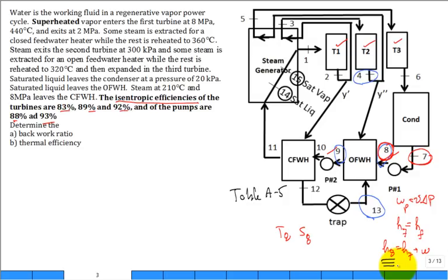I got h8, pressure at 8. So you got the pressure at 8, enthalpy at 8. Good luck going to that table. You may probably have to do a double interpolation, but you can get an estimate, not good to 3 significant figures from my experience, but at least you'll get an estimate of both the T8 and the S8. And if you wanted to, why stop there? v8, u8. I mean, come on. It's just a game of getting properties.